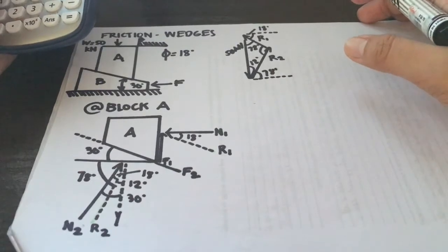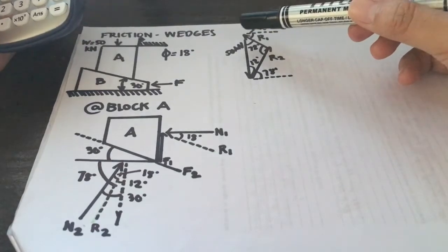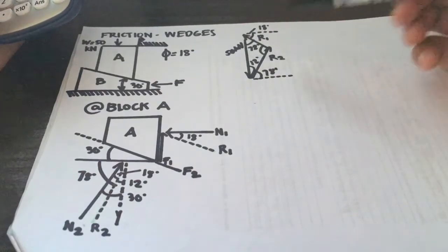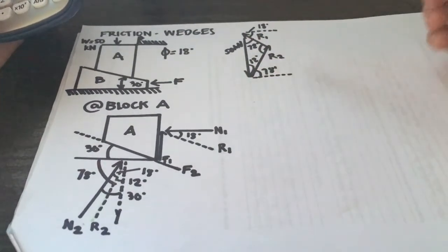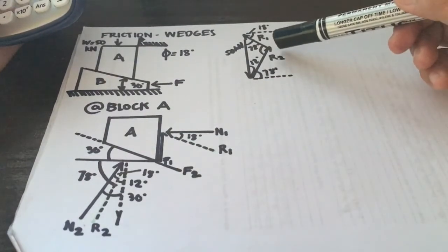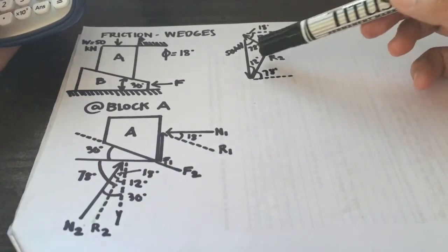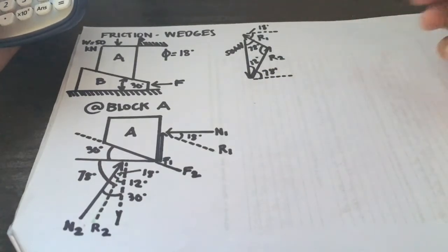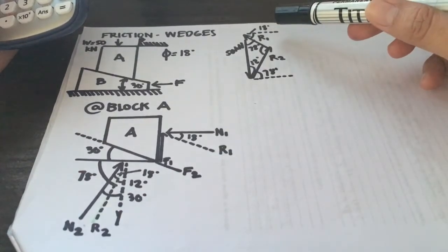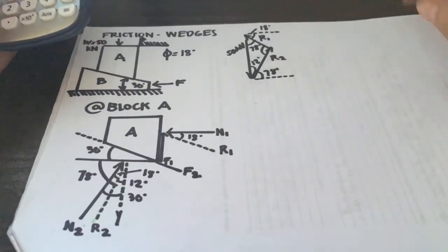Now is the time that you can make your force triangle. First, put the 50 kN, which is the weight force, here. Next is R2, located here, which is at 78 degrees with respect to the x-axis, therefore you have 12 degrees here. And next is R1, which is at 18 degrees with respect to the horizontal axis, so you have 72 degrees.